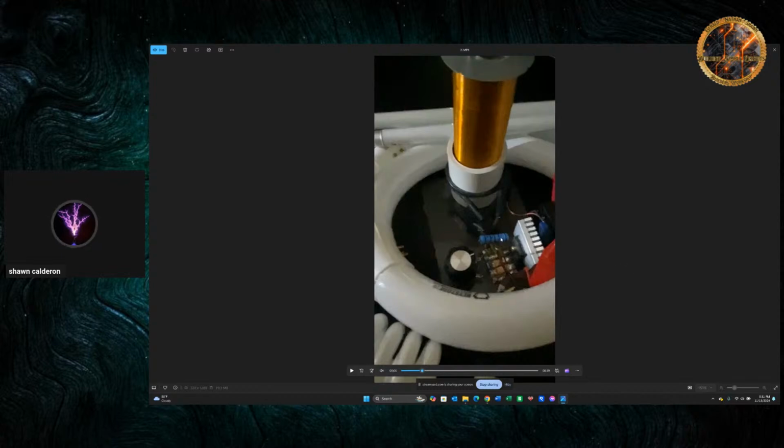Instead of one resistor, I have two. I have one here, the blue here you can see. And then I have a potentiometer, a pot here, that's just a resistor that you can turn the knob and adjust the resistive value. And so this is a very tiny circuit. This coil here is not even 3 inches tall, and it's an inch wide. It only has a couple hundred turns of thin wire on it. So this is about as weak as a Slayer exciter coil that you can build.